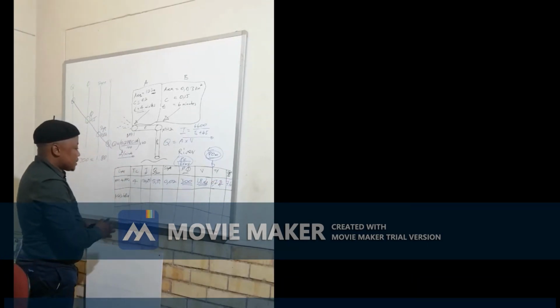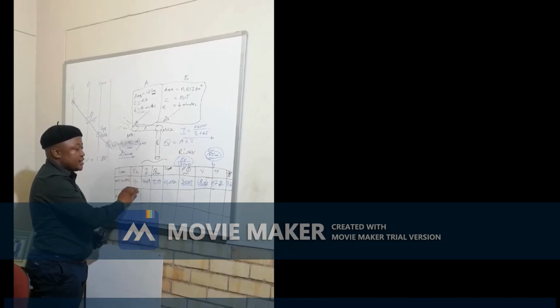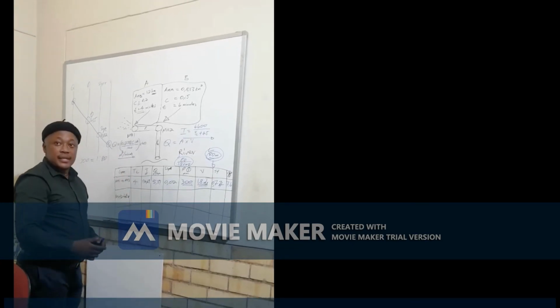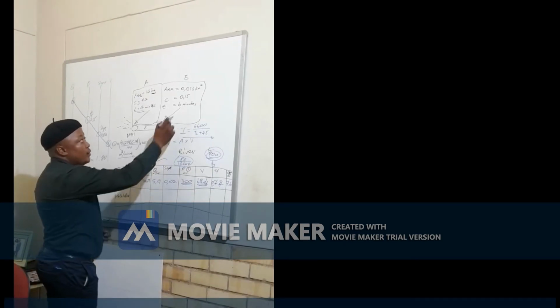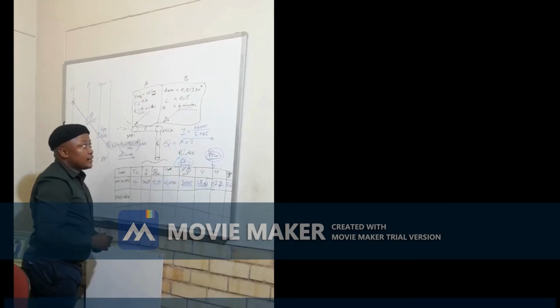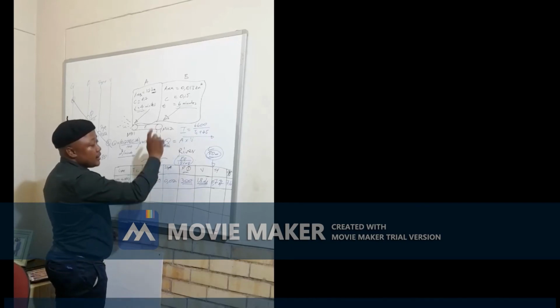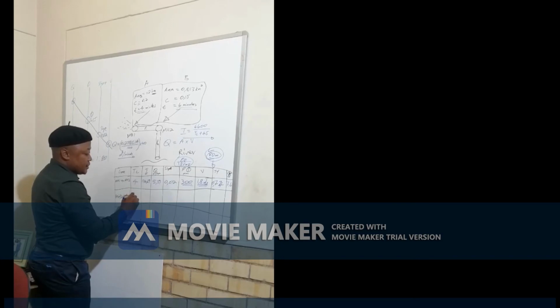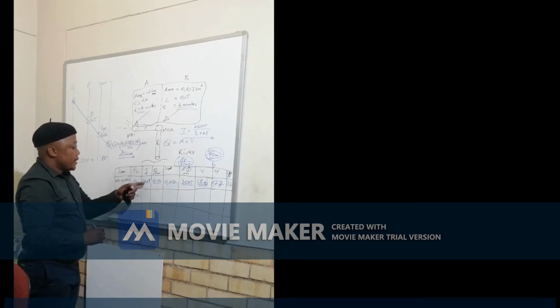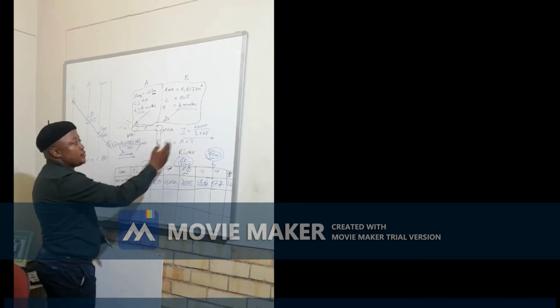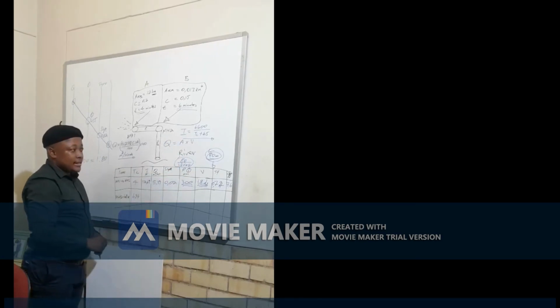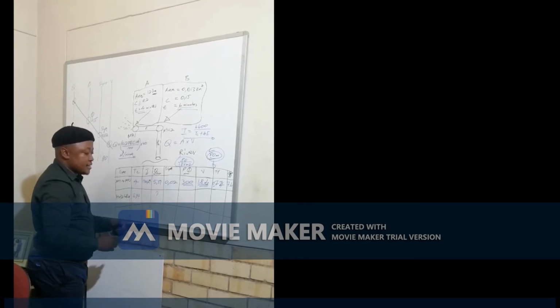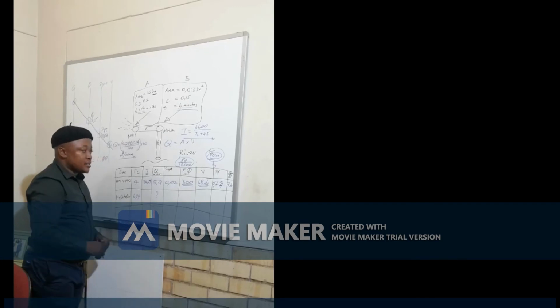Now when you move to the next line, remembering that the time of concentration was time of flow plus inlet time. However, in this regard, we've already acquired the inlet time as well as the time of flow. Hence, we'll be having a different situation in terms of our time of concentration. And then the I, again, you go back and substitute based on the variables exactly the way we followed on that one.